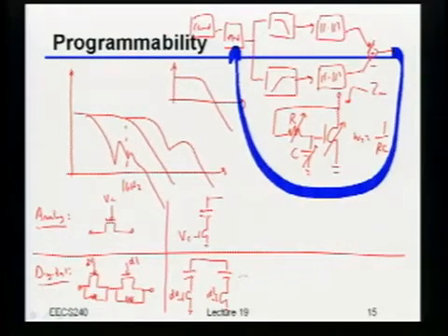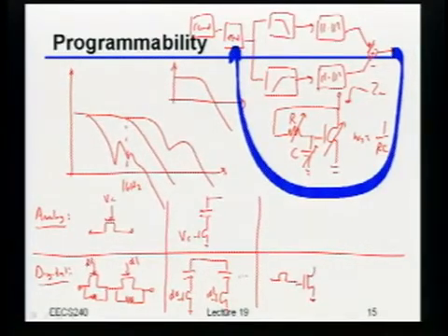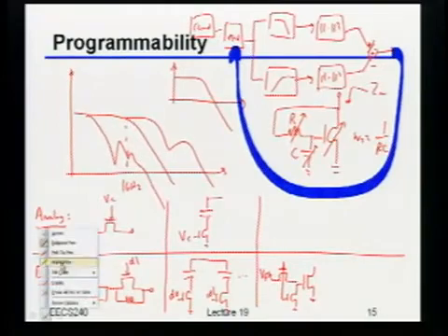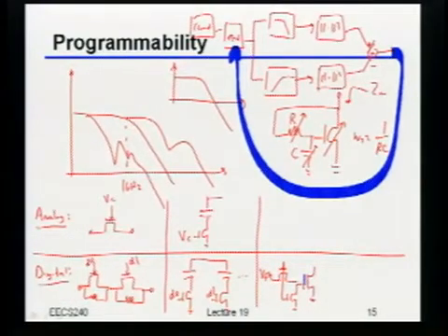Okay, so just last and very briefly, just for the sake of completeness, if you wanted to tune, as an example, the GM of that active inductor, that's kind of like saying you want to tune the size of the transistor. Well, the way you could do that is doing something like this. And again, I'm going to just draw the digital one because that's a little bit easier. But basically, imagine that this was like your V feedback or whatever. So you could take that V feedback, and either you connect it to the gate of the transistor, or you just shut that transistor off, right?